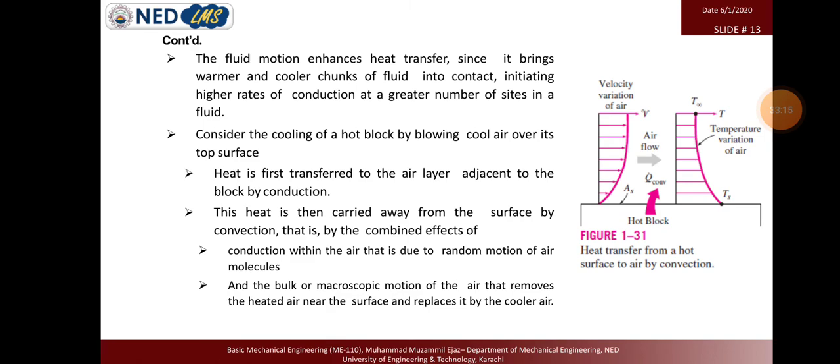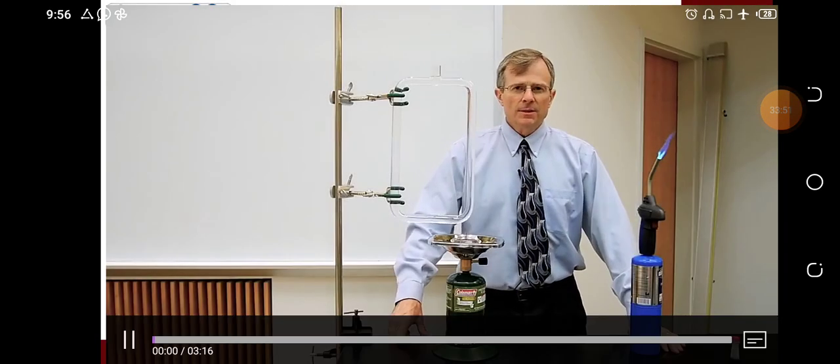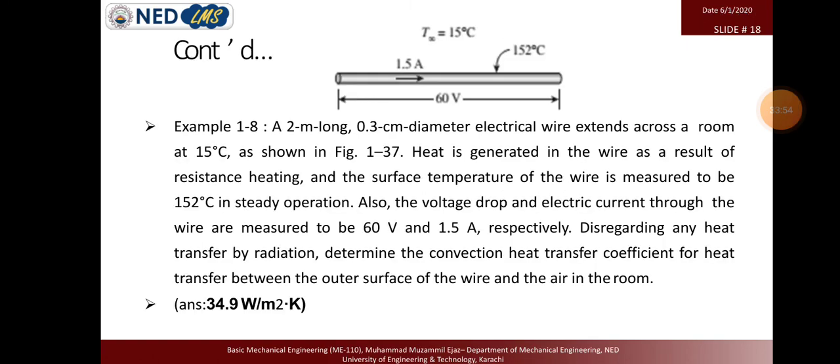I just explained this to avoid any difficulty or complications in your thoughts about what kind of temperature T infinity should be taken. So I hope you will understand. You can take the uniform temperature over here, but you also need to take the value of h as a uniform or average heat transfer coefficient. But if you take the T infinity value over here, you also need to take the local h value, the local heat transfer coefficient. There will be different kinds of values.